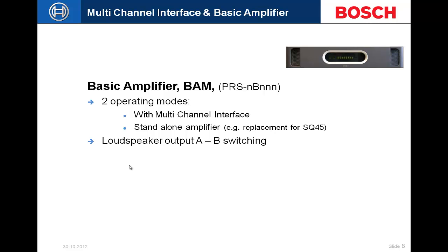Loudspeaker A+B switching. Essentially, we can do a Class A wire loop system. What that means is we can essentially have a type of self-healing speaker wired network. So if there was a break within my ring of speaker wire, it would essentially self-heal that speaker ring and give me a notification on my console and on my network controller or connected logging viewer and server, I would be notified that that speaker wire had been cut. However, my speakers in a Class A loop system would keep functioning.